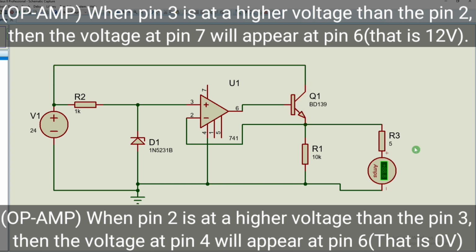For this purpose I need a capacitor over here. So I will add a capacitor just like this, so that when this circuit is cut off, it will start giving current to this load. The moment the voltage increases, the connection will cut down, and the moment it decreases, this connection will break down, and this capacitor will continue supplying this 5 volt power supply.